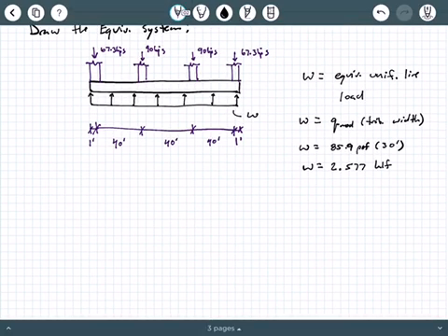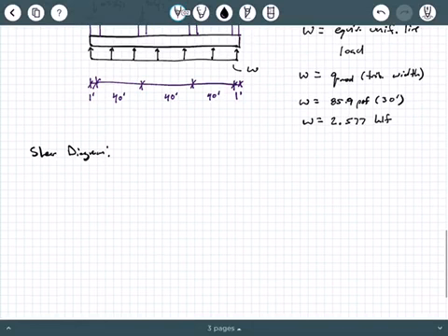All right, so check this out. This system, because we've made proper adjustments and we've taken things that are happening on the entire slab and adjusted them to distribute things properly on one strip, should be in static equilibrium. So we're not really having to solve for any reactions per se here. We're ready to go right into the shear force diagram. So we're going to say shear diagram.